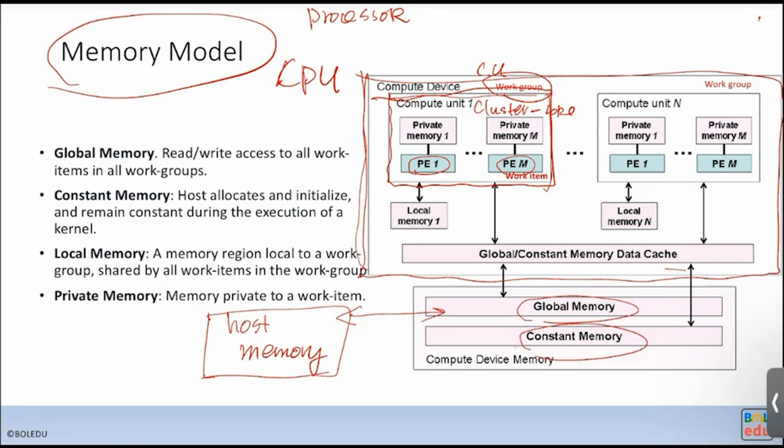Inside the CPU, for example, you have a 32 core CPU. For Intel, because 32 cores sharing a cache would have too much traffic and the distance would be too far, they partition the CPU cores and also partition the cache memory hierarchy. For each CPU core, you can think of the PE as a CPU core, and it accesses the private memory. The private memory corresponds to a level 1 cache, the level 1 instruction or data cache.